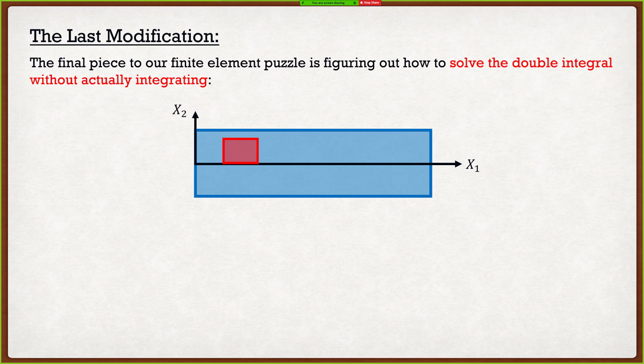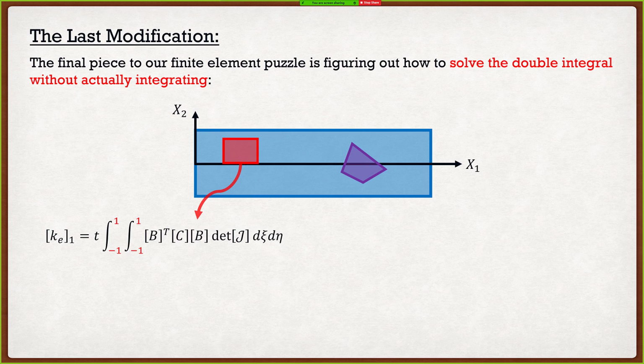And I said that after our isoparametric formulation, we have a nice formula for our stiffness matrix. Now, if I had a distorted element on the other side, well, I still have my nice isoparametric formulation. I have a formula for that stiffness matrix.